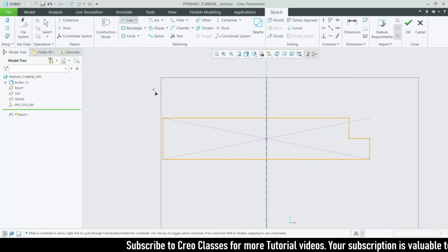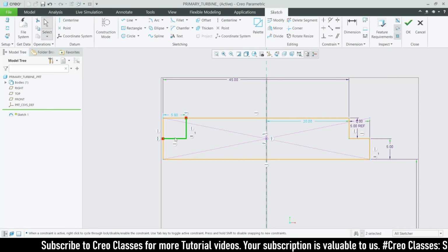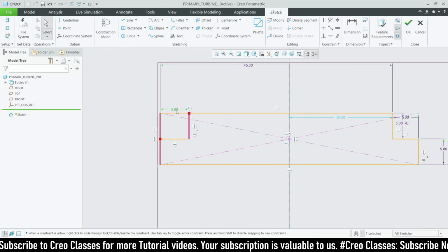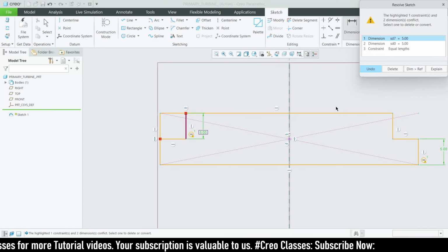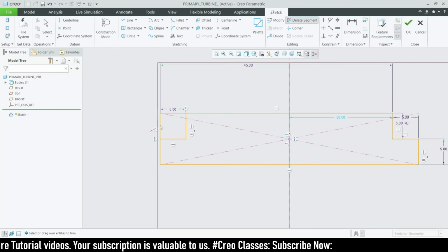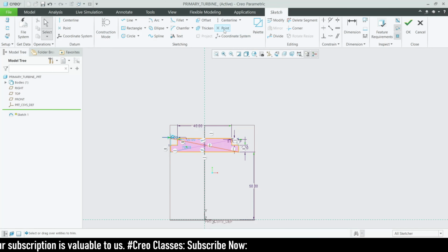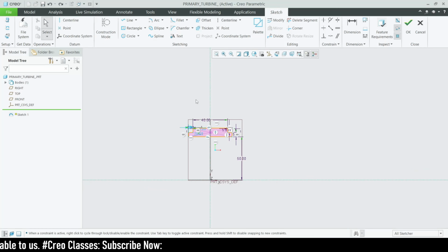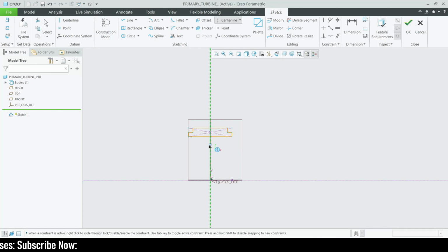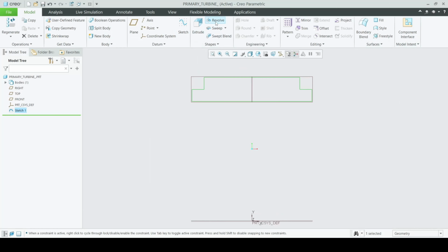And the same on the other side, you can also mirror this part, but I don't want to mirror because sometimes it may have some error on this. So 5, and let's check this height whether it is 5. Okay, 5. Okay, now let's delete this. Now I have completed our sketch. So we can directly go for the revolve and then we can go for the next part. Okay, sorry. Okay, center line like this. Okay, 5 and 5.